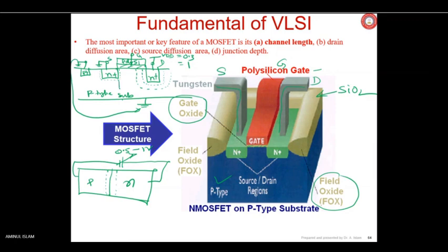Okay, remember that this is the channel length, original channel length L, but due to depletion layer, due to increase in VDS, drain to source voltage, the depletion layer delta L amount decreases the effective channel length. So effective channel length is nothing but, let me write in this way, L effective equals L minus delta L. Are you getting the point? The carrier has to cross this barrier, entering into the depletion layer, and quickly going to the drain terminal because there is a strong electrical field there, so it is being passed to the drain terminal.